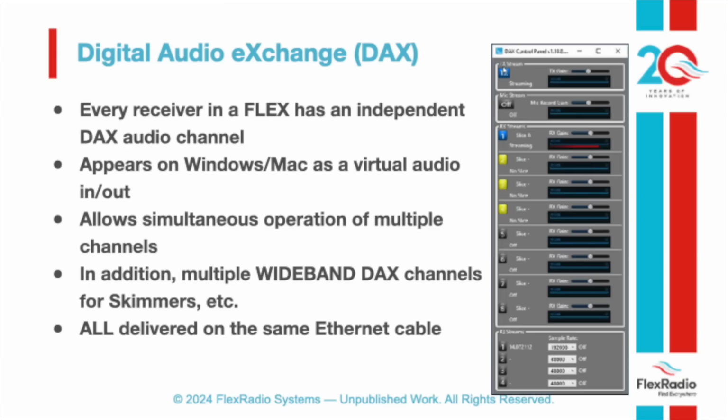We also have a unique capability called digital audio exchange, which allows you to take streams of digital data out of the radio, pipe them over to Windows or Mac, and then use them for digital modes like FT8. You get a control panel that looks like this, where you can control each of those streams, run them to different IP addresses, whatever you want to do, and it gives you a lot of flexibility around doing digital modes with this radio. This is a very unique capability. All of the digital modes are shipped over the Ethernet cable, so you don't need extra interfaces or cables. All the data goes across the Ethernet into your computer and then shows up as a sound card.